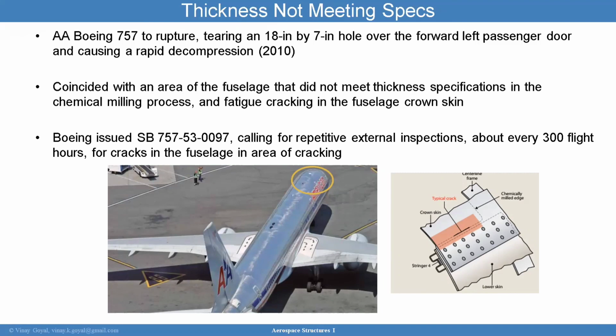Good. Yes, certainly, quality control. Once the section has been produced, someone comes in and checks the dimensional compliance of the part or the assembly. Very good. But maybe even before that, before the part or the assembly gets manufactured. In finite element analysis. Finite element analysis could have helped us for sure, just to simulate, okay, what happens if there's a crack here, what would be the rate of propagation, what would be the end effect. That's a good point. But let me ask, before running a simulation, how could you have known that a simulation can deliver important answers to you?